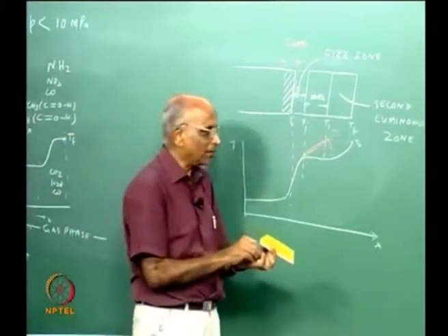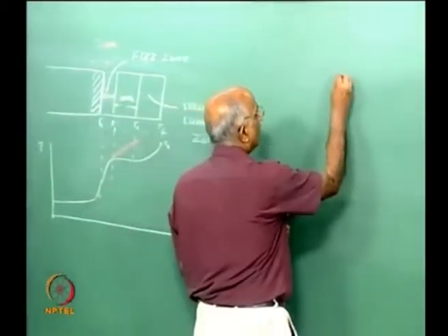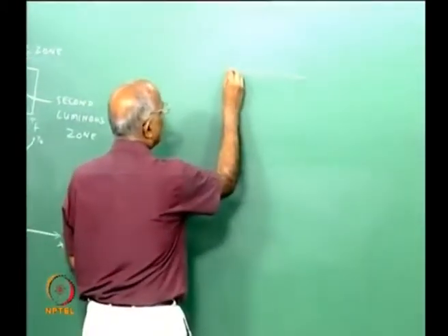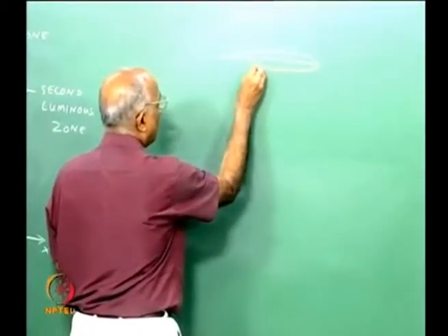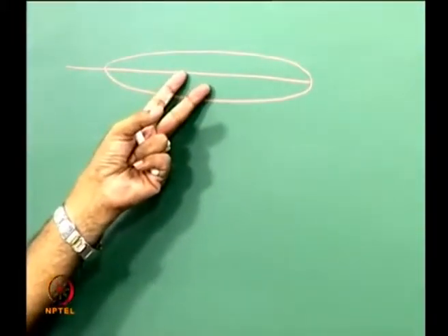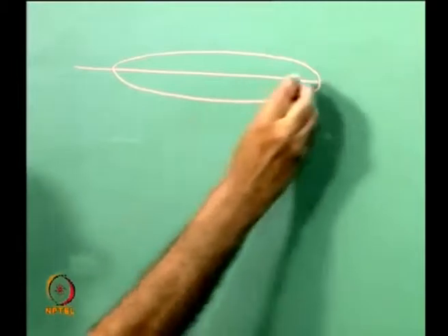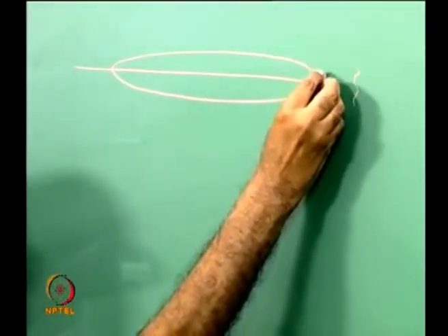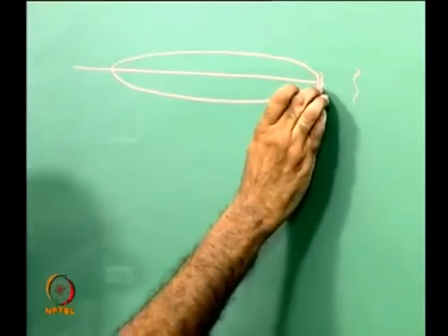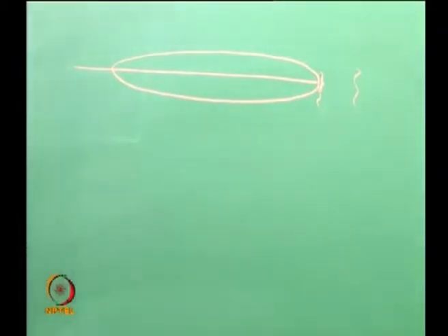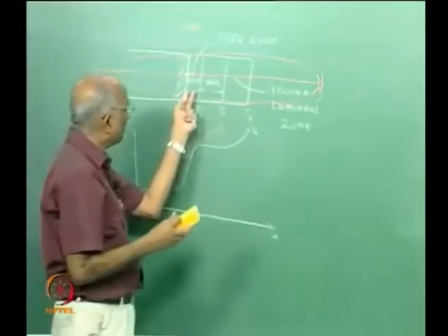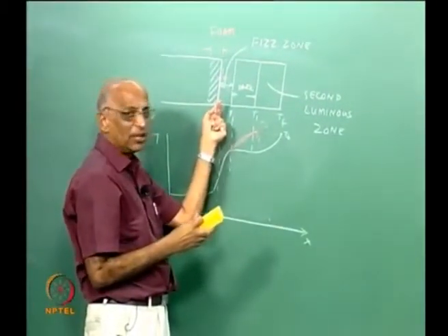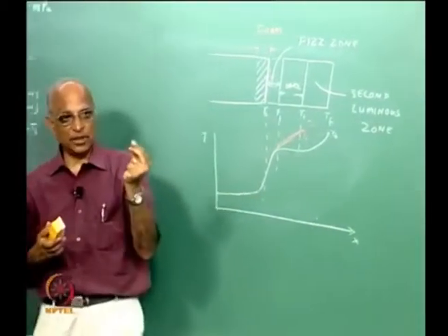What happened in the sparkler? You had a rod, you coated the propellant over here, and what was this propellant? KNO3 plus carbon plus sulfur all bonded in it. We found right here itself gas is getting generated. The reaction distances are all within a fraction of an mm, even for that. Therefore you can imagine we are talking of distances which are a fraction of a millimeter thick.